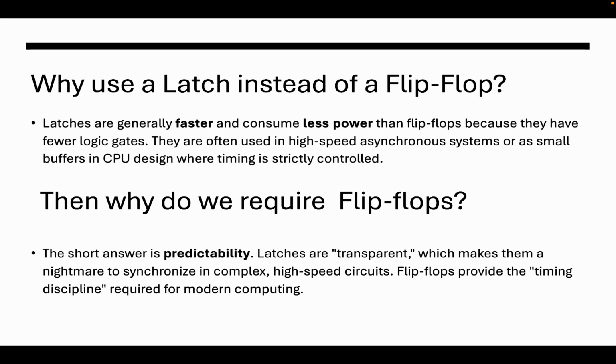Why do you use a latch instead of a flip-flop? Latches are generally faster and consume less power than flip-flops because they have fewer logic gates. They're often used in high-speed asynchronous systems or as small buffers in CPU design where timing is strictly controlled.